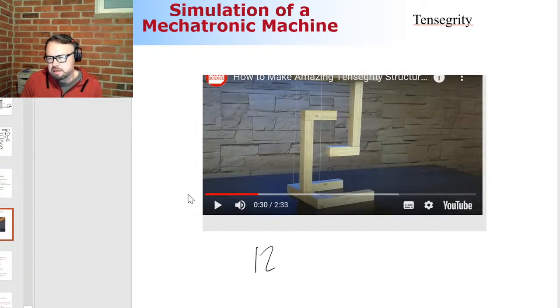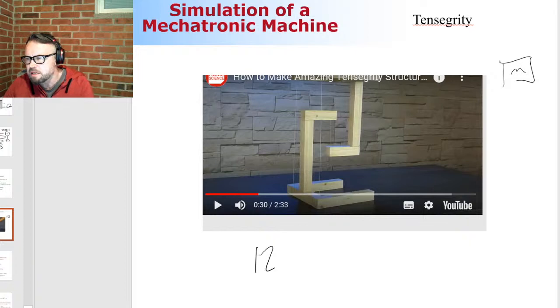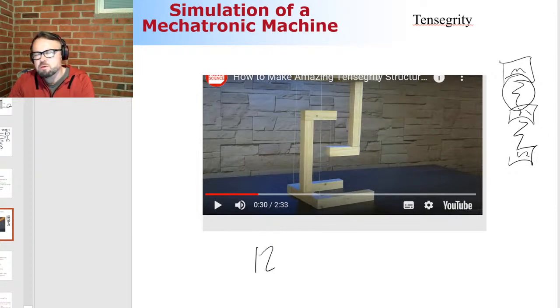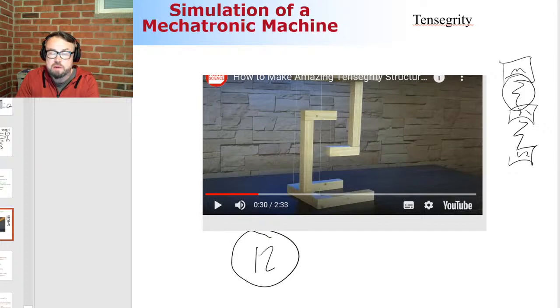They are connected together via ropes. Ropes are not motion limitation. They are acting like a system that is constrained, but seriously, they are not a motion limitation. So they are not constraints. Remember, in the very beginning, in the first lecture, there was a mechanism with a mass and spring, like this. These springs are not removing the motion possibilities. Because they don't remove the motion possibilities, theoretically, the number of degrees of freedom in this system is 12.